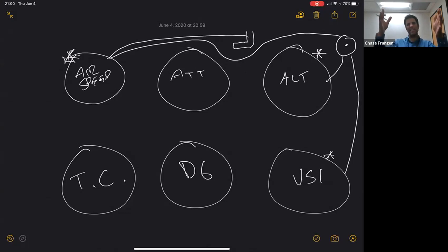If you've ever seen an old school thermometer with the little blobs of liquid that rise and fall based upon the temperature, I kind of think of aneroid wafers like that, but they are calibrated to certain pressures, and they expand and contract if the pressure inside of the instrument is different than them. Those wafers are connected to a series of gears that directly change the hands on the altimeter. For somebody who's grown up around technology my entire life, this is a really hard concept to understand. It's hard to imagine these blobs sitting inside of the altimeter that change in shape based upon the barometric pressure of your surroundings, and drive a series of mechanical linkages that then change the hands on the instrument, but that's the way it works.